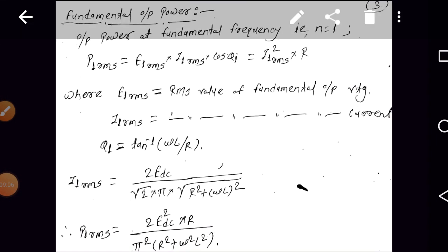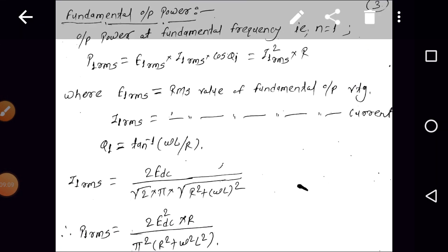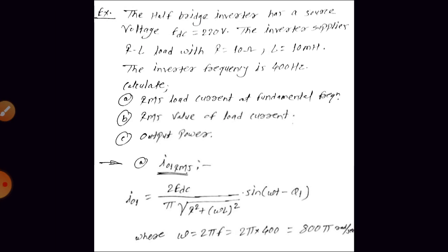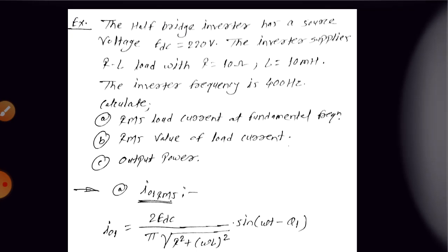So are you getting the point, right? As long as the load changes from R to the RL load, there will be some changes in the expression of load current, right? And here we need to consider the angle of lagging also.